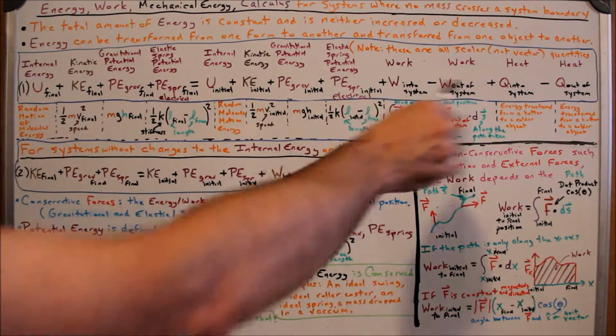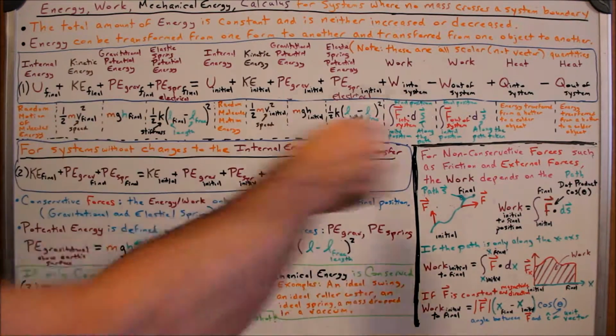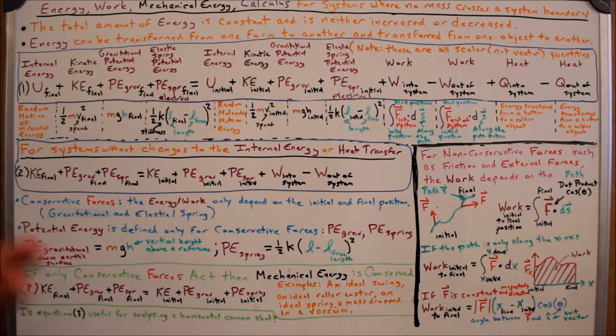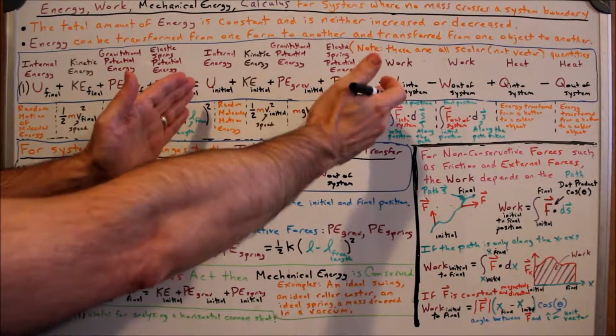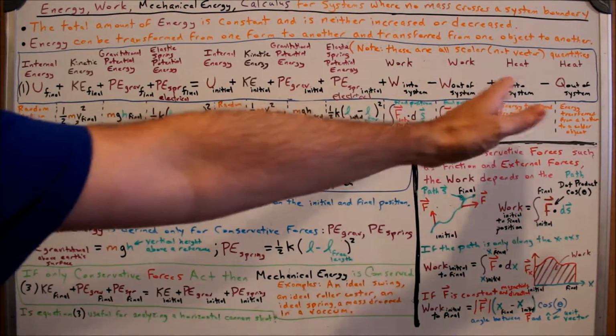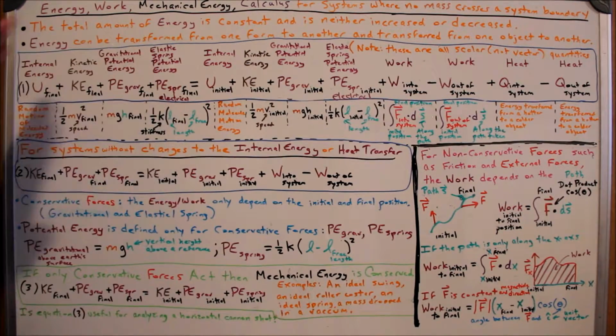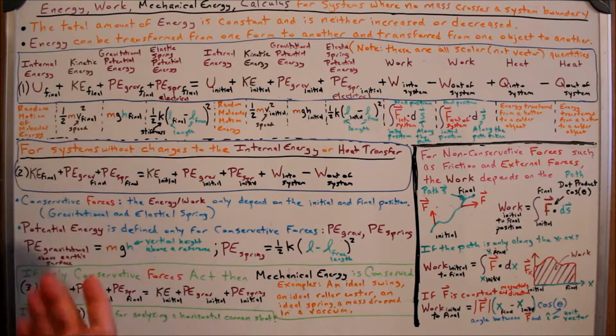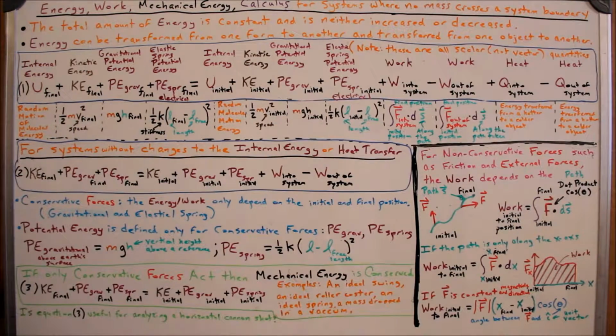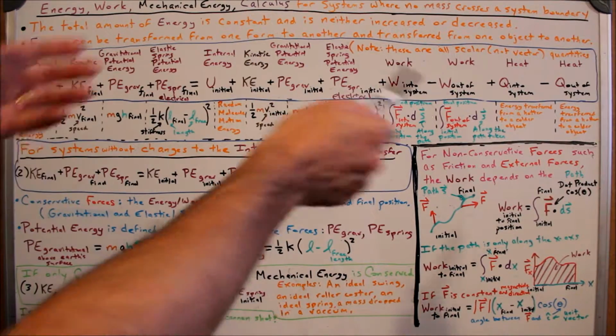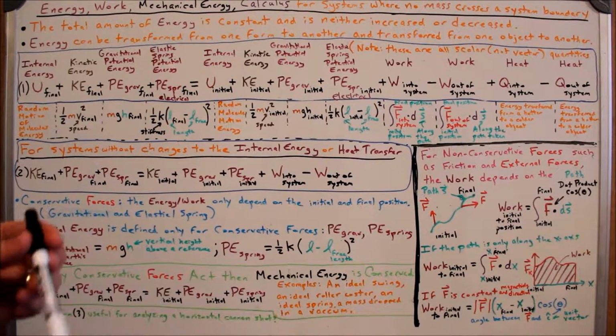And so typically we want to think of energy as a balance. I have a very long equation I call equation number 1 right here. This is a form to help you understand some initial energy in as many forms, and I can put energy into the system or take energy out of the system, and then I'll have some energy of the system at the end state. So that's my energy balance. It's sometimes helpful to write it out almost in its entirety, and you should be very careful: if you don't include a term, that term is 0 or insignificant.